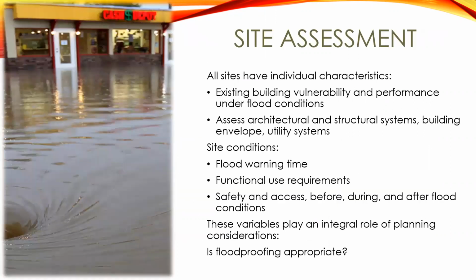If we're talking about an existing building, in the site assessment we have to determine whether dry floodproofing is an appropriate thing to do based on the structural and architectural integrity of the building. Can it withstand having these implementations added onto it?